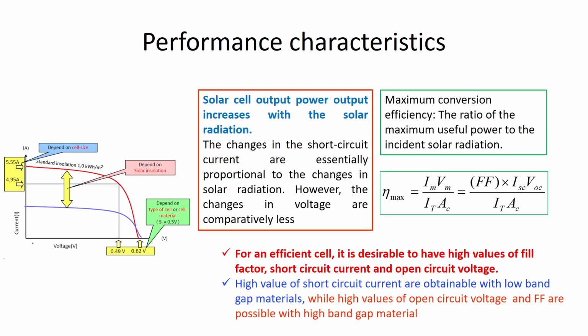So, what you can see here, this is the IV characteristics curve at solar radiation say I1, and this may be at I2. Okay. So, I2 is greater than I1. That is how it appears, something like this. And when intensity is more, then we will have higher ISC value. So, we will have this kind of thing.